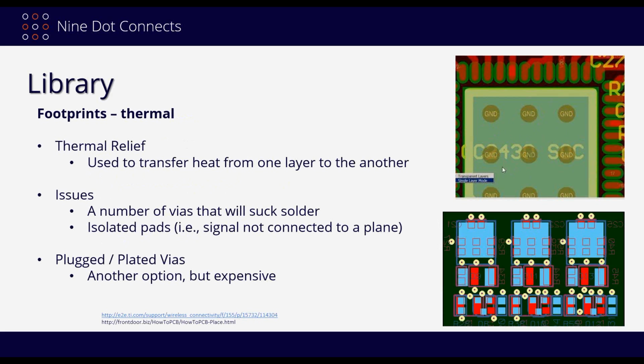So if you do want to have a pad in the middle and you want it to connect to those things that are on the plane, you have to be a little bit more savvy about it. Here's a great example down here where you have this pad, and then they've got the solder mask around here so it won't wick into these via holes or through-hole pads. So they still have electrical connectivity, which in turn will provide thermal connectivity, but that solder is not going to be racing down these holes because it's barriered off by the solder mask.